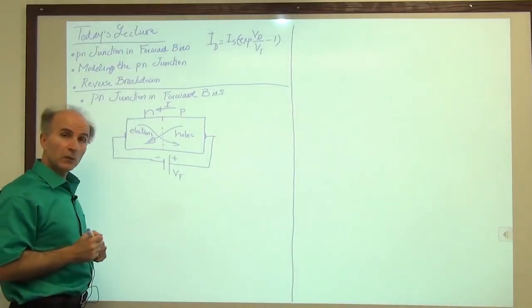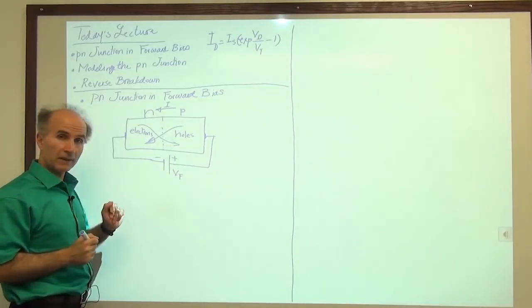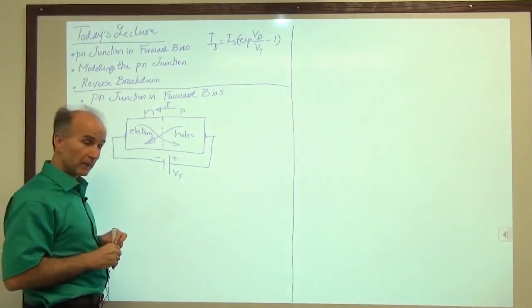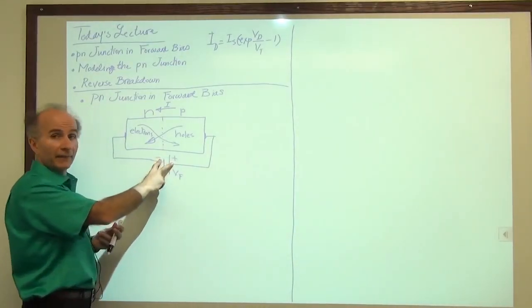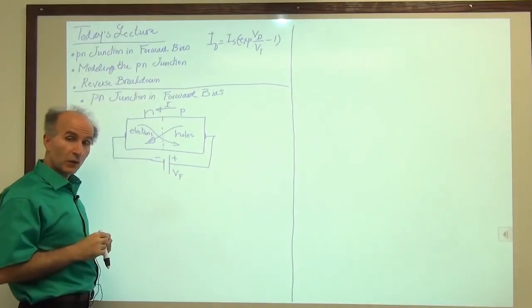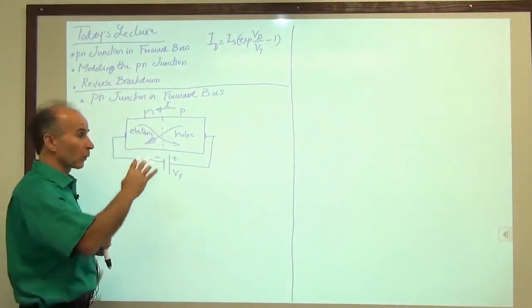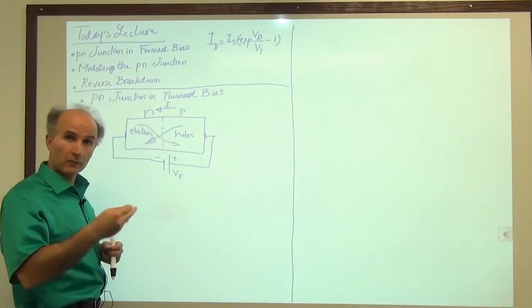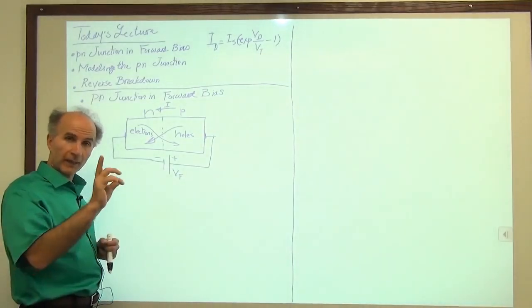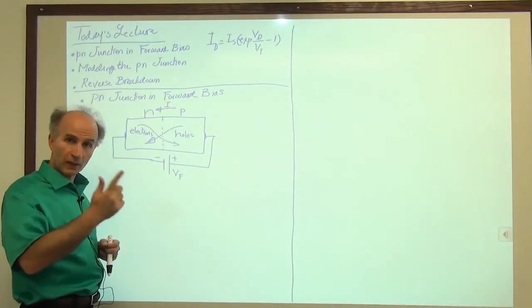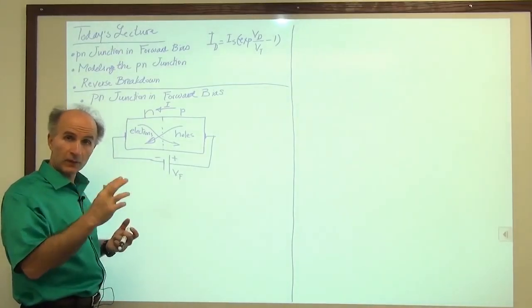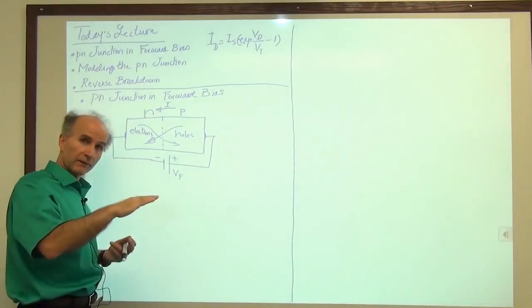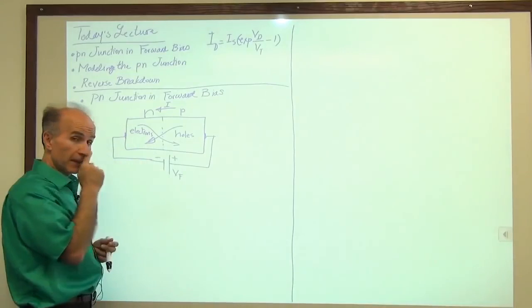So that's interesting. We see that if we choose the voltage polarity like this, then we have a current through this junction. In reverse bias, when the voltage was the other way, we didn't have any current. The current was very small. So that's a big distinction between what this device can do and what resistors can do. For a resistor that we saw in basic circuit theory courses, we never thought about the current going one way or another. We always thought these two have to follow the voltage. So you go from positive voltage to negative voltage, the current goes from a positive amount to a negative amount. But now we see that it's a very different story.